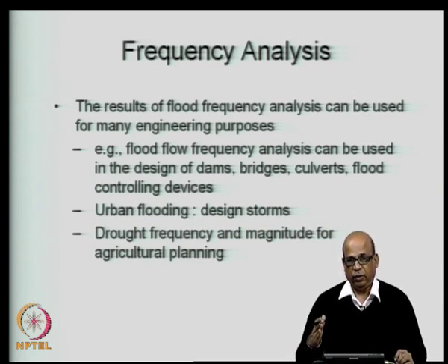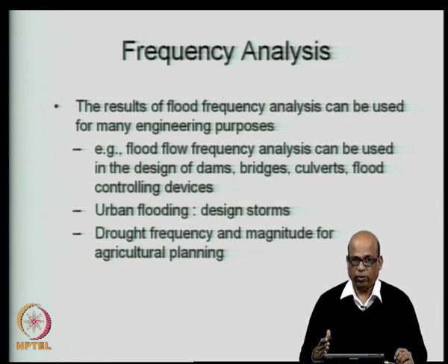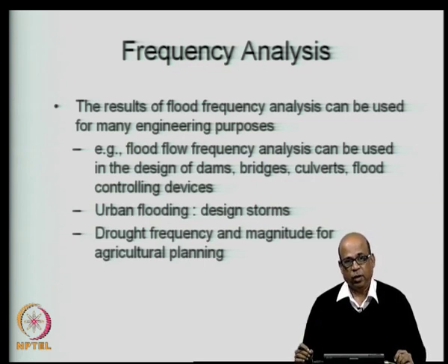Let us say that this year a flood of a given magnitude has occurred, then we will be interested in what is the probability that it will occur again next year, or the average time that may elapse between occurrence of this event successively. Does it occur once in 5 years, once in 10 years and so on.